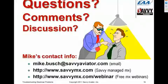Many aircraft have a separate bus for avionics with an avionics master switch that can be turned on and off. Some aircraft have a hot battery bus, which is a bus that is hot continuously even when the battery master is turned off, and is used for things like clocks and courtesy lights and things that you want to operate even when the master switch is turned off.